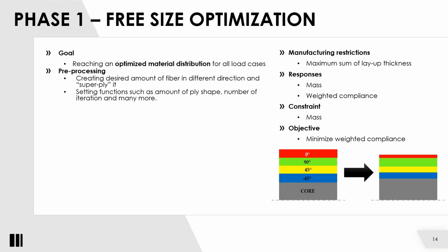So we set up a maximum mass, which is the target mass of our monocoque, which we get from our overall vehicle goals. We set a target weight for our car, and then you can distribute the mass across the sub-teams. Then we say we want a monocoque with 15 kilograms, so we set up a maximum of 15 kilograms for our monocoque and see what happens.